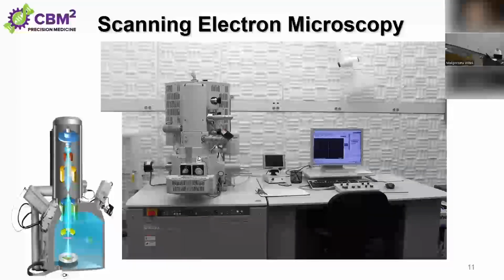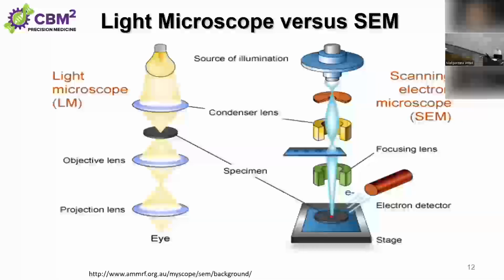Scanning electron microscopy. Well, Dr. Park already kind of explained that to you, believe it or not. The only difference is instead of using an ion, you're using an electron. Ion versus electron, what are the differences? Well, an ion is going to be heavier. An electron is going to be very, very light, so to speak. So what does that mean? Well, when I take an ion like gallium and accelerate it and impinge it on a surface, it's going to blow material away, ablate it, just like Dr. Park talked about. An electron, not so.